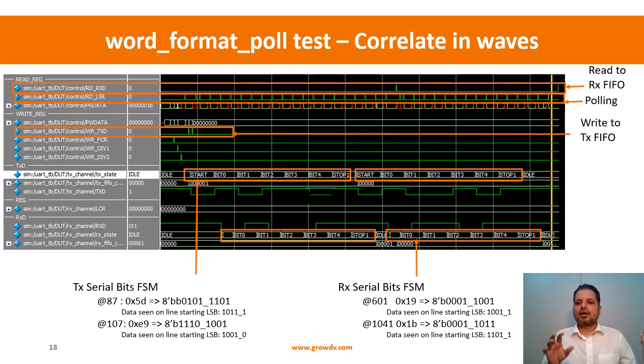But in debugging, the error message would be saying, okay, I was expecting this byte, but I have gotten this byte. Then what you will do is, from that point you will first spot it in the waveform and backtrace to the point where the actual value, whatever value has come, deviated from the expected value. That is how you do it.